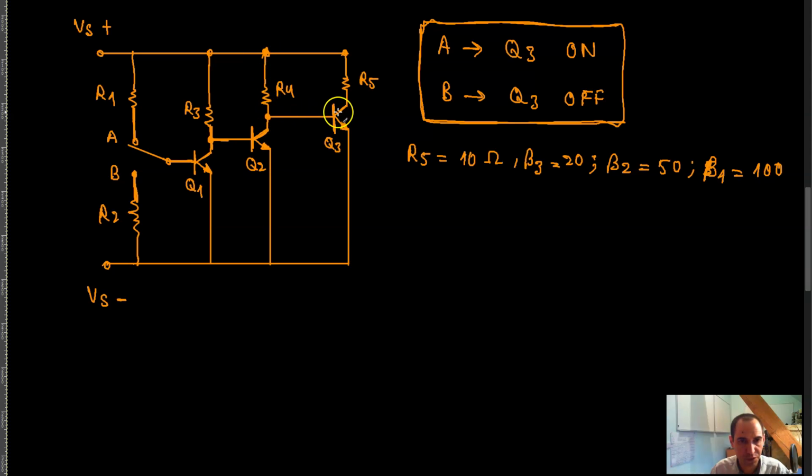It comes down to the base of the transistor, goes to the emitter to the ground, and this current through the base emitter junction has to be large enough so that it causes a large enough current in the collector emitter path so that the transistor is turned on properly. So first I need to know how much current I need in the collector emitter junction of Q3.